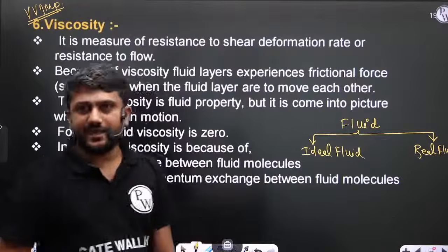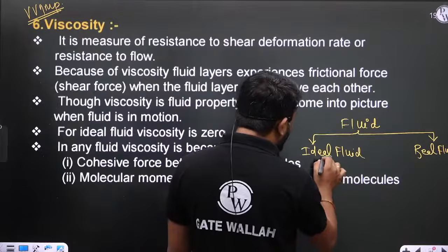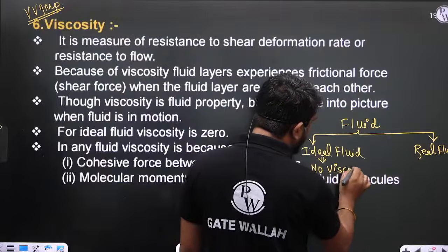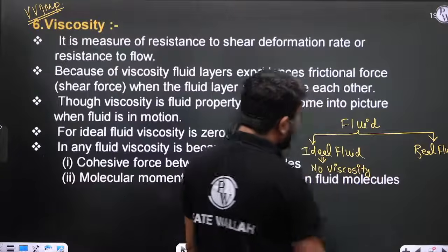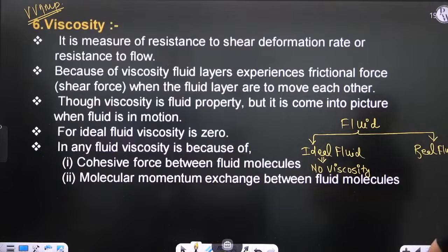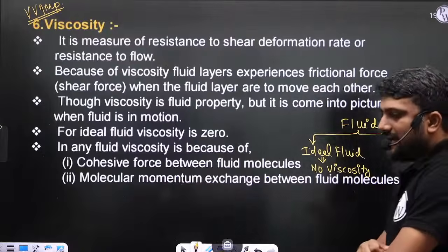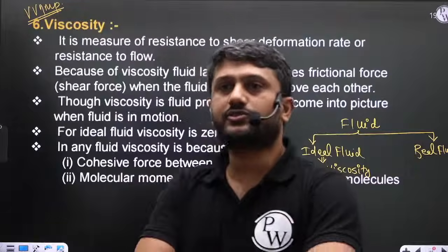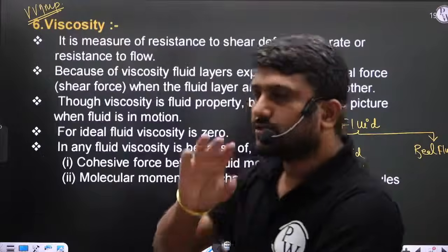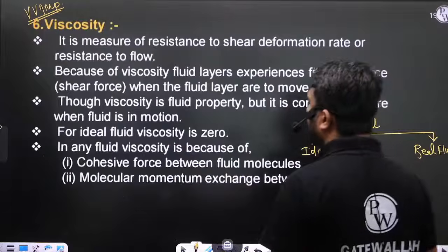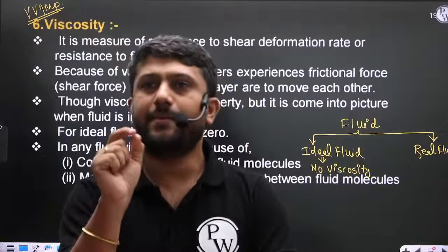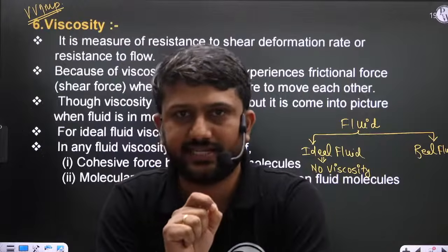So if I'm talking about the ideal fluid, the ideal fluid has zero viscosity, or we can say no viscosity. And what is the reason of viscosity in any fluid? Viscosity is because of the cohesive force between the fluid molecules, and the second important factor is the molecular momentum exchange, right?